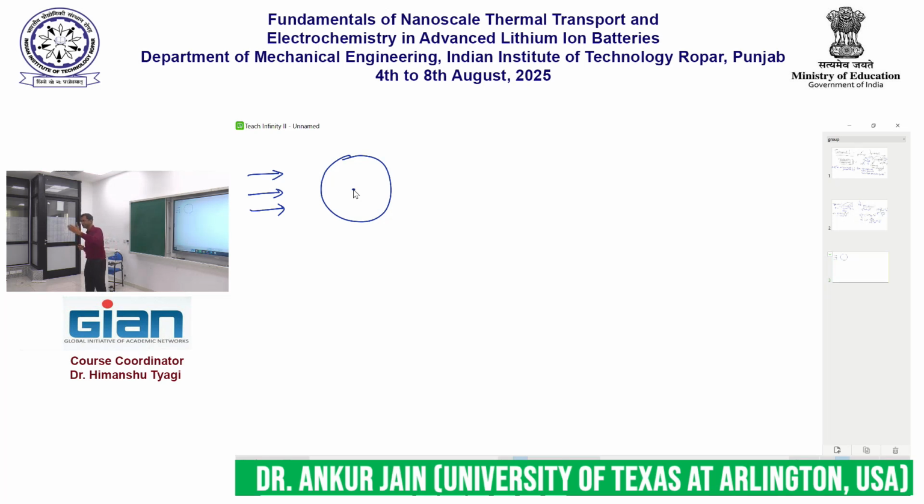And we will learn in tomorrow's very first lecture that thermal imbalance within the cell is a big problem. Not only do you want to cool down the cell, but you also want to cool it down as uniformly as possible. If one part of the cell is very cool and the other part of the cell is very hot, then that is not desirable as well. The temperature gradient inside the cell should be minimized as much as possible. And that is one problem that happens in a cylindrical lithium ion cell.